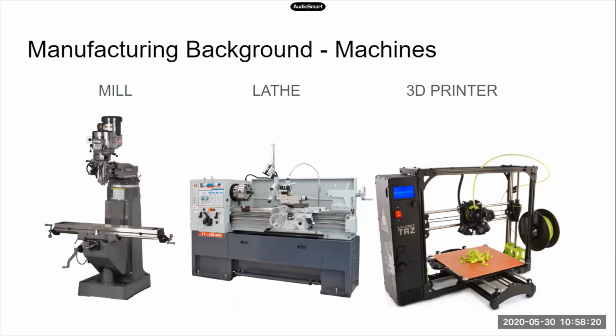I've been working on CNCs before when the person who made the machine code wasn't necessarily the person who secured the work in place to be CNC'd. And if you put your tool paths to navigate places, but you accidentally put the hardware to hold your work in the way, bad things happen. I do not recommend. I have been the recipient of many flying drill bits and sparks from running full speed into steel bolts. So it's a bit of an experience to figure out how to hold your work without interfering with tool paths and stuff like that.